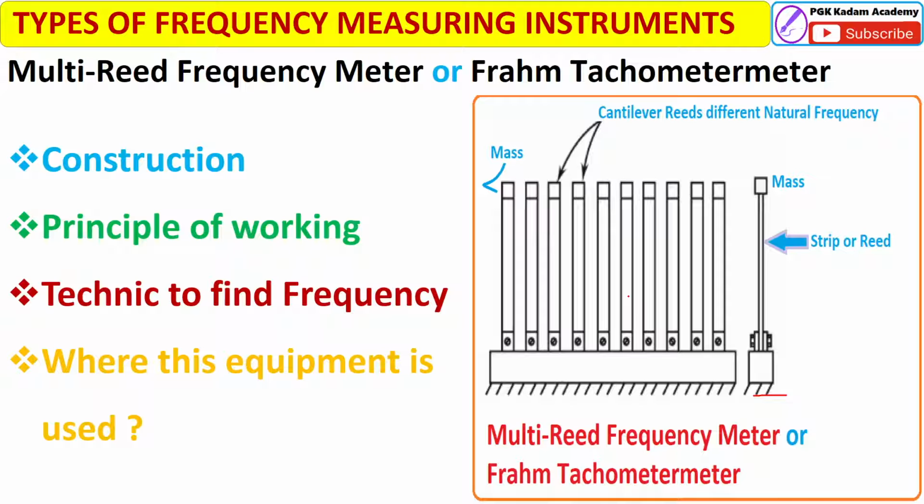So friends, here what will happen: the multi-reed frequency meter, also called the Frahm tachometer, consists of a number of strips or reeds in the form of cantilevers, carrying small masses at their free ends. Each reed has a different natural frequency according to the mark on it.